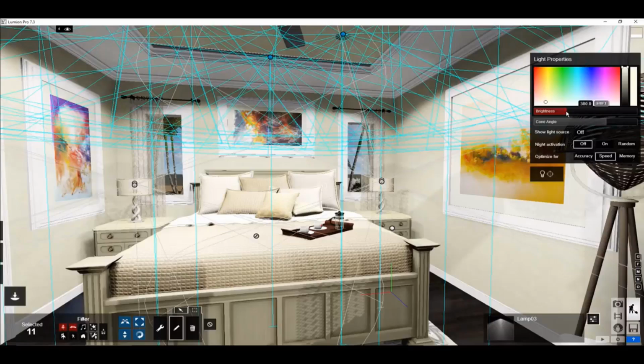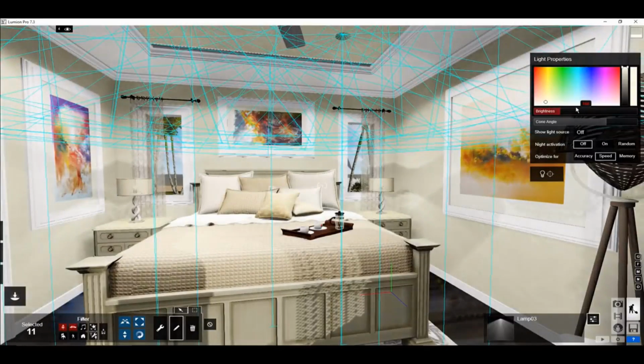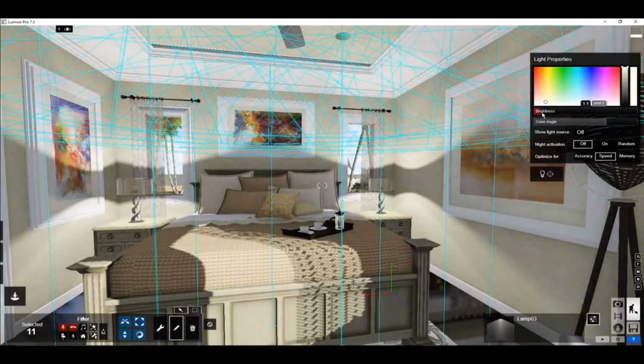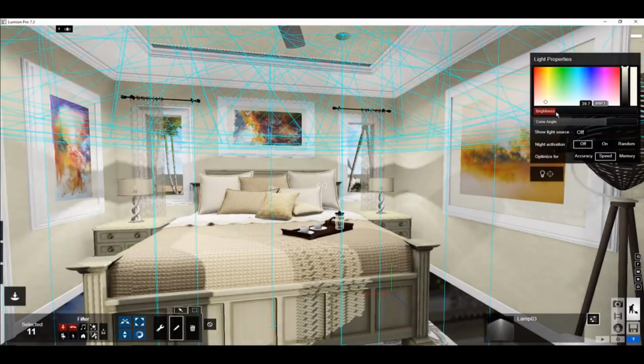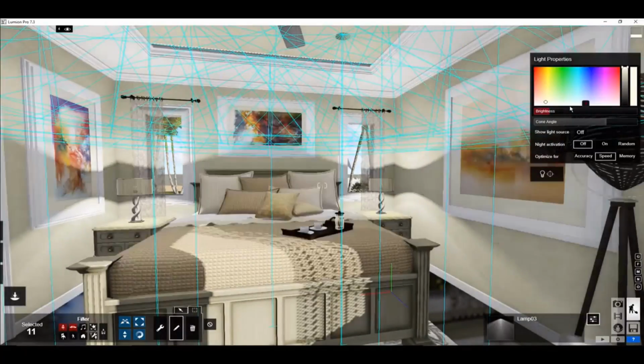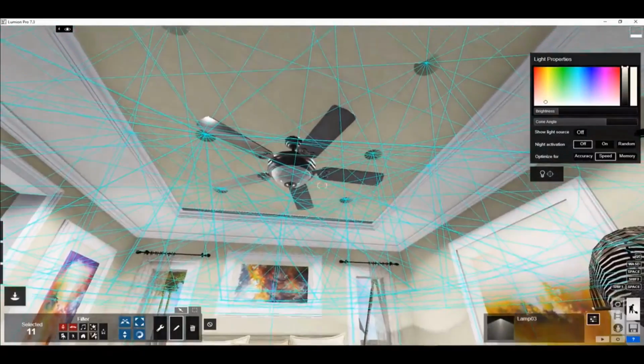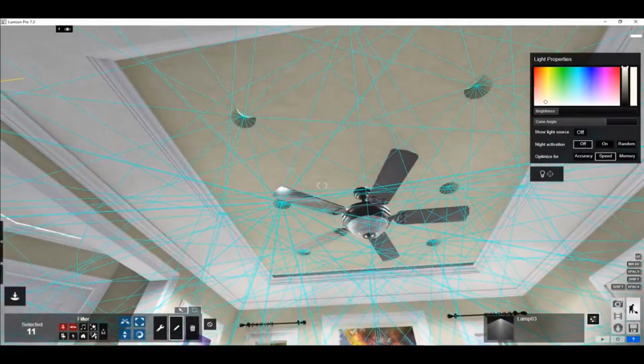So let me double click on this. You can double click on any of these sliders in Lumion and hit backspace. And maybe we try 100, or let's just slide this thing around. So here's 0. As I start inching forward, around 50 it makes an actual impact. And around 100, it's glowing pretty bright. So I might stick with 75 for this light source. So again, keep the lights low. All right, so that looks good.